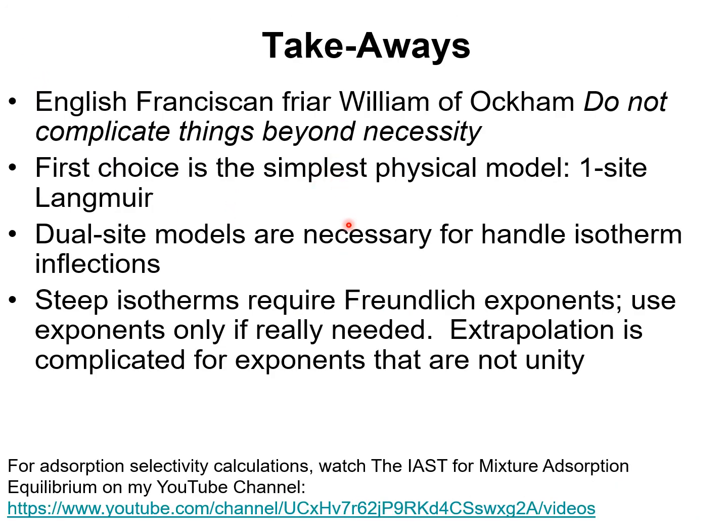For fitting unary isotherms, we need to adopt Occam's razor. Do not complicate things beyond necessity. We start with the simplest physical model, the single-site Langmuir model, and only resort to more complex models such as the dual-site Langmuir model or the dual-site Langmuir-Freundlich model if the unary isotherm data cannot be described adequately using simpler models. For example, isotherm inflections require the recognition that there may be two different sites for adsorption within the MOF framework.